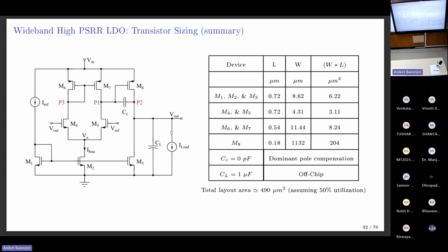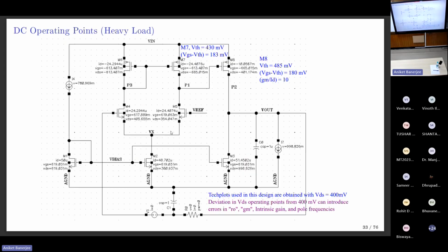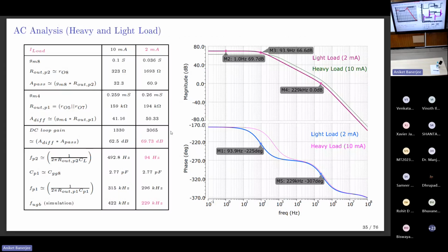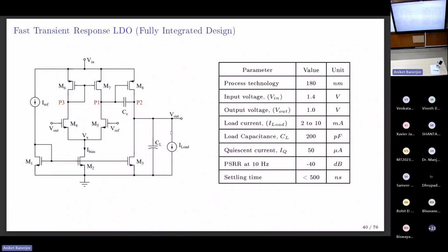One more question: all three topologies using the op-amp are designed, so do I need to look for different topologies of op-amp? If you want to meet a very high DC gain and a very fast transient response, with maybe moderate current, then you look at the folded cascode topology. In this case, we have taken this topology only as an example. This is applicable to all other topologies, even all other circuits. You can design LNAs and LC oscillators using this methodology. This methodology ties W by L to the performance measure.